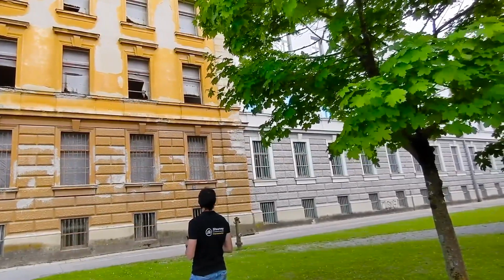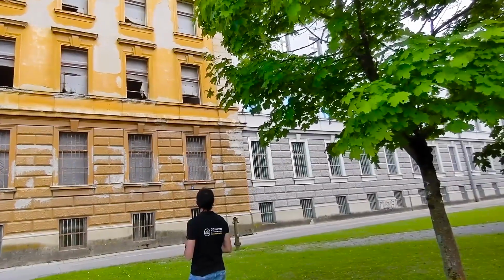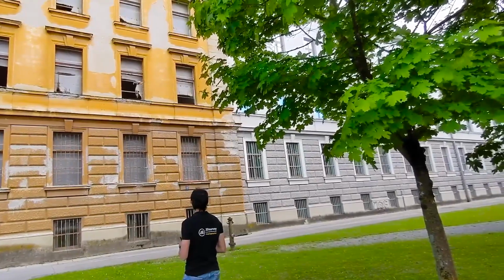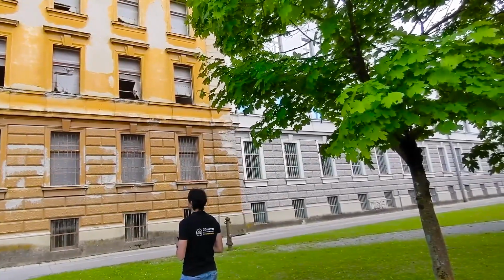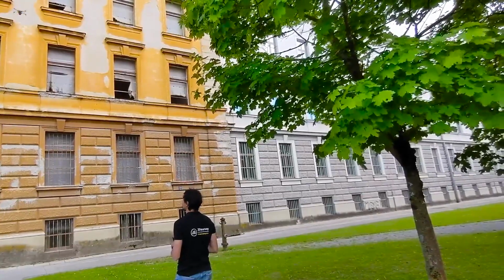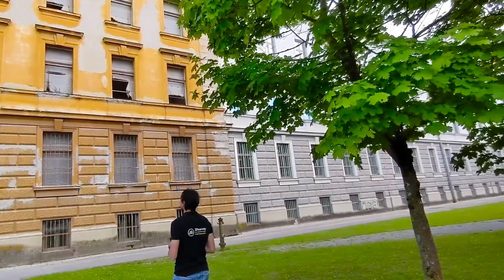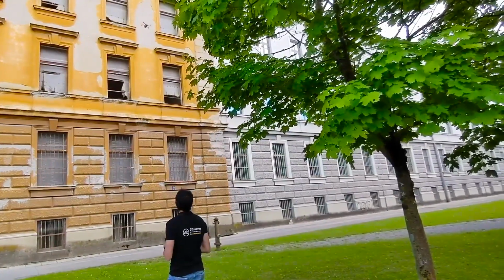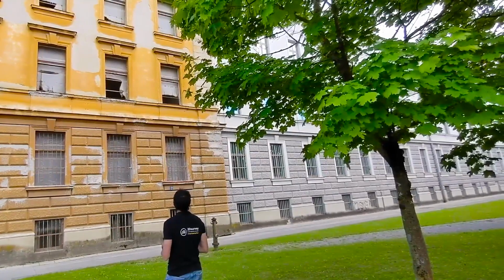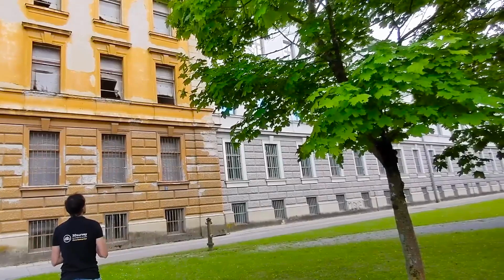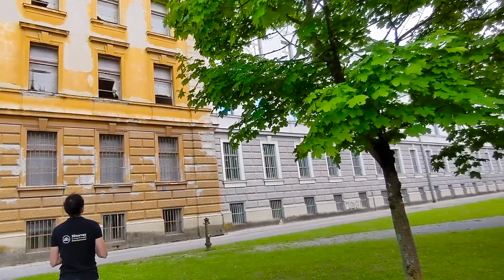As you can see, I'm flying in a horizontal way, stopping every 2 meters and just triggering images, and then raising my flight an additional 2 meters, and flying back and triggering the camera. So it's actually super simple. Just for your feeling, I'm about 5 meters away from the objects because I really like to have images with good quality, with high resolution, because this will deliver me at the end a nice point cloud and great orthophoto.